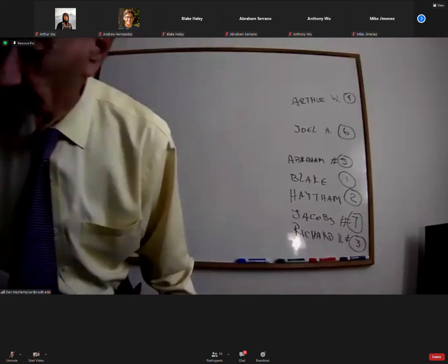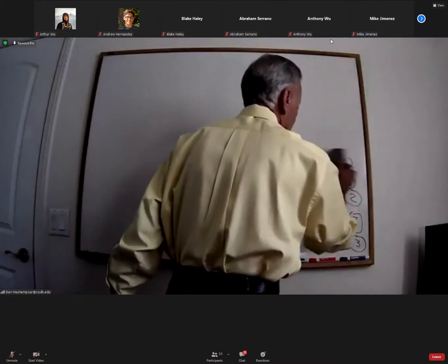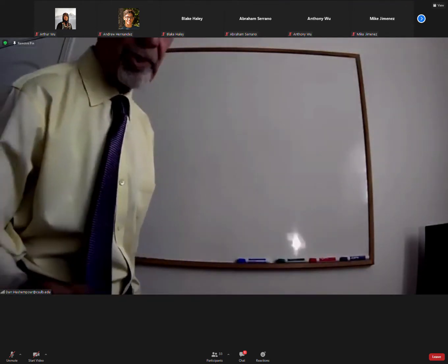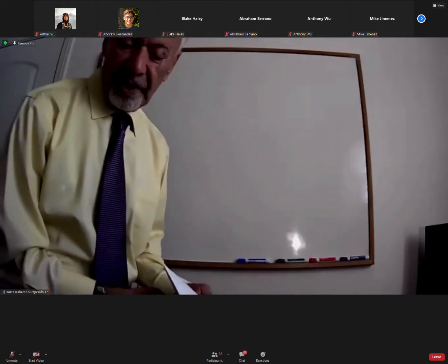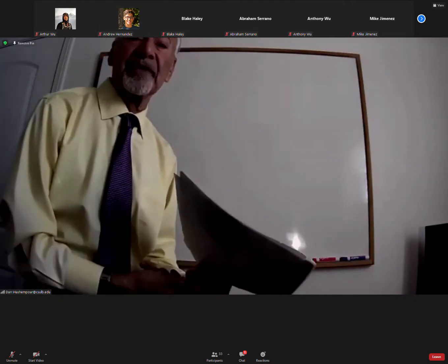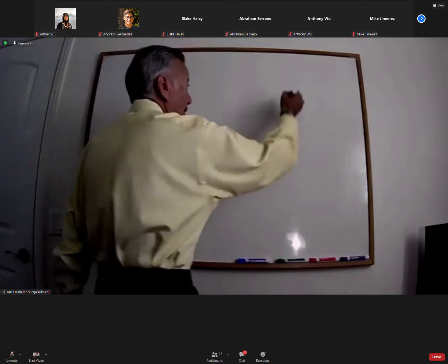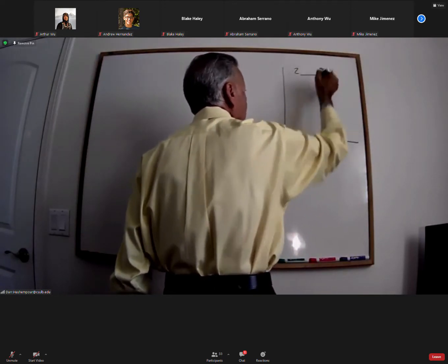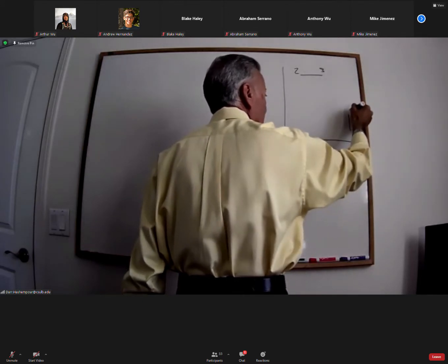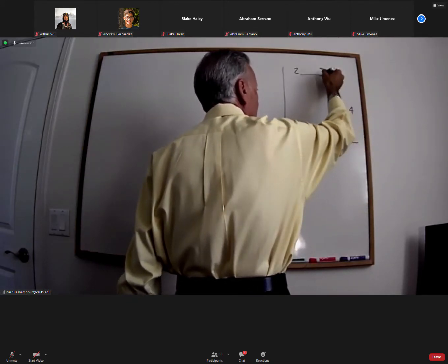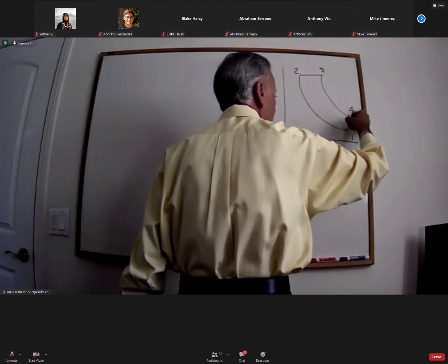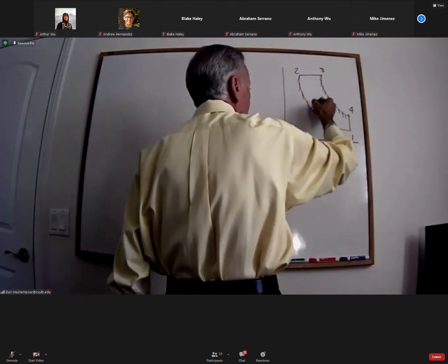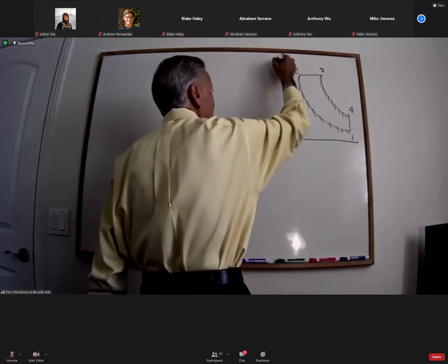Again, I'm not gonna draw the equipment diagram because you already saw it; for the Otto cycle and diesel cycle, they all look the same anyway. We need to have the PV diagram, though. Process 2 to 3 is constant pressure, process 4 to 1 is constant volume, and this is where we are constant entropy, or isentropic. That's our PV diagram.